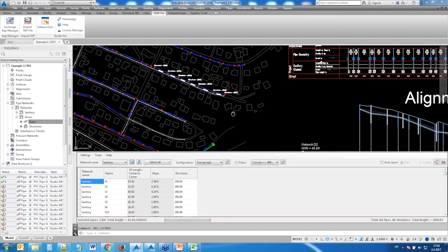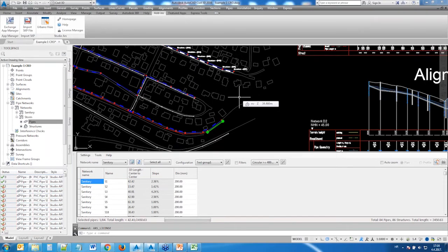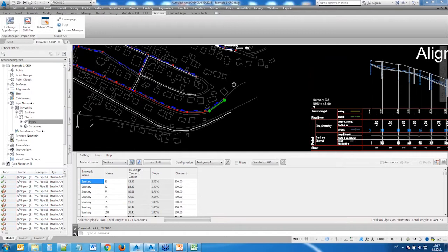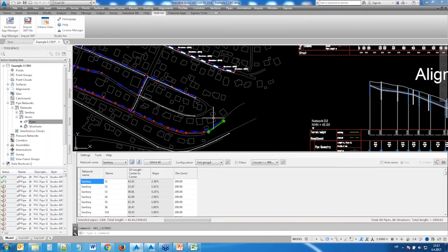Okay, and the way I created this group for pipes, in the same way I can create a group for structures, except of course I will select from a different data group from Civil 3D. Okay. So the other important thing is with the pipe vista and structure vista, you're always selecting the whole project. With Urbano Visio, it's not necessary.